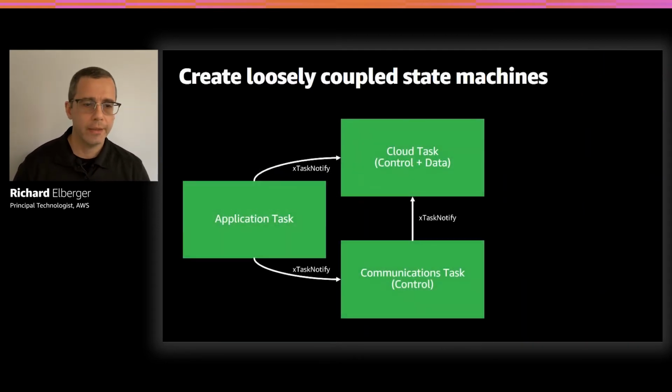When you're connecting to the cloud, and that means IoT Core's MQTT broker, as you know, you first need a socket connection from the microcontroller to the cloud using the communications module we talked about in the previous section. We see that represented here in the communications task. That task is responsible for proper module management: enabling the module, initializing it, and then commissioning the configuration as you need it. For example, connecting to an access point and getting the IP address from DHCP. You need to do all of that stuff. We take that for granted on our laptops. Also, you need to take care of all the teardown, like disconnecting from the AP and putting the module to sleep to save power. This is one state machine that we need to effectively manage here.